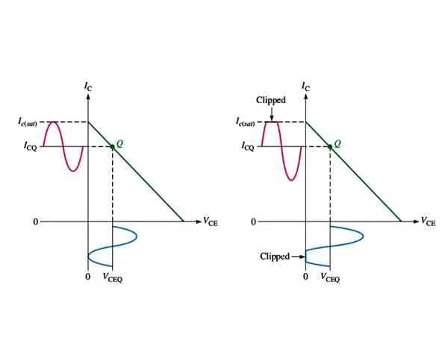Figure here shows an AC load line with the Q point moved away from the center towards saturation. In this case, the output variation is limited by saturation. The collector current can only swing up to near saturation and an equal amount below ICQ. The collector to emitter voltage can only swing down to its saturation value and an equal amount above VCEQ. If the amplifier is driven any further, it will clip at saturation as shown in part B of the figure.